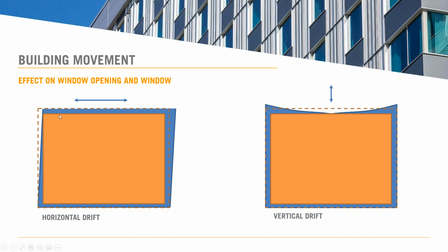So imagine if your window is solidly attached on all four sides, a window frame coming from the factory is not designed to change shape. You want your window with that nice piece of glass in it to stay square and stay attached. So how do we do that? First, we attach at the sill, and then ideally, we want our attachment to accommodate these two different types of movement. So let's look at this with the actual attachment types in front of us.